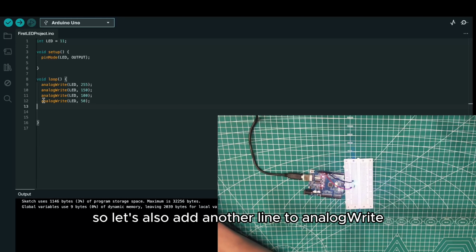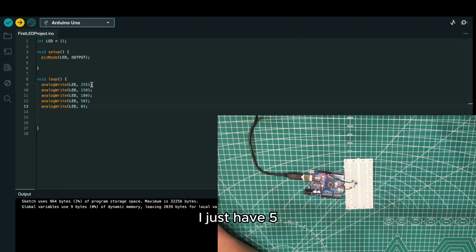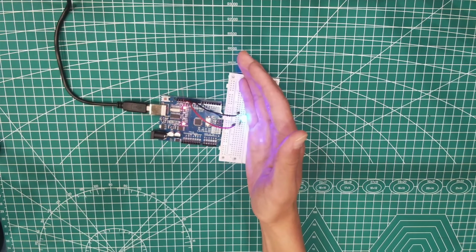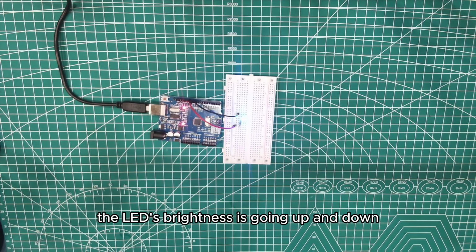So let's also add another line to analog write. It really doesn't matter, it depends on you. You can put as many as you want. I just have 5, ranging from a value of 255 all the way to 0. And now, once that is done, as you can see, the LED's brightness is going up and down.